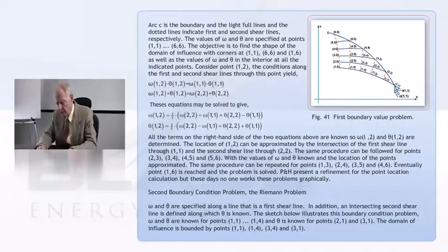Okay. Then, knowing theta, you know which way the shear line is directed as it goes through those points, the different angles, of course. And if I take a short enough little element, then I can draw a first and second shear line through each of those points. And that'll determine, if I started out the way I said, I would determine omega and theta at point 1, 2.